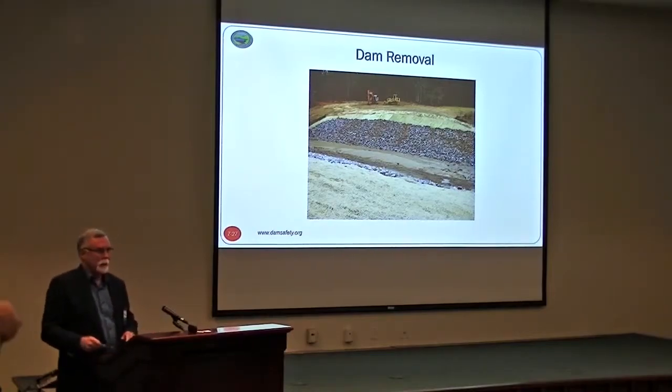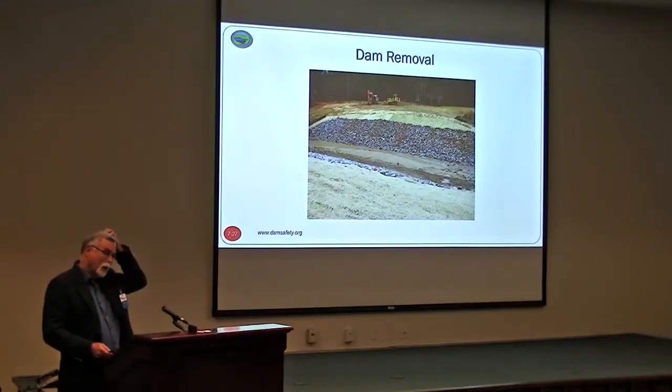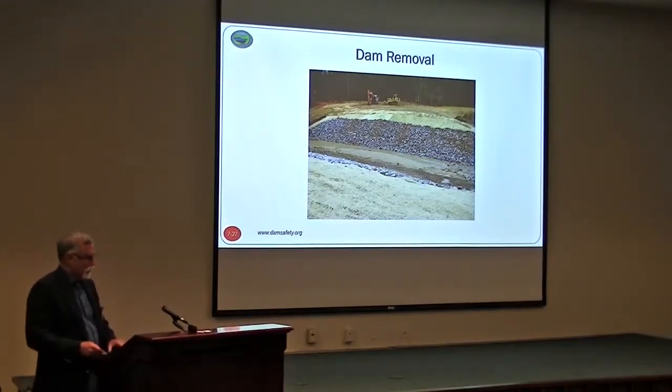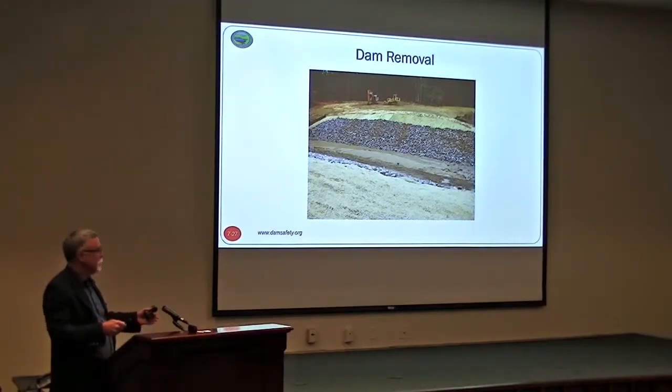Now, if you can't fix your dam, he said the other option is to remove all of it, or breach the dam. And you got to be careful. Here's one where you got to make the breach width wide enough so it doesn't still back up. We let part of the dam in place. You put riprap in so it doesn't create an erosion and sediment problem downstream.